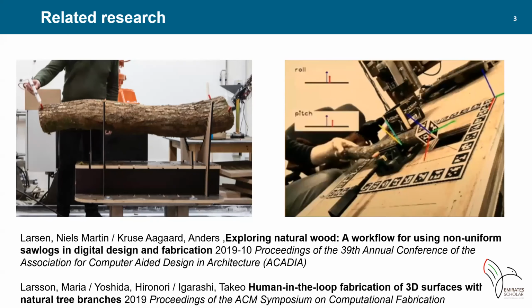There have been cases of direct processing of logs before our study. Most log processing systems do not allow free repositioning. This is because if the posture of the workpiece during machining is different from when the shape is measured, the difference in posture needs to be handled, and measurement of posture change is not easy. In this case, the posture is tracked by attaching a jig to logs, which enables machining with different postures. However, it is necessary to prepare as many jigs as there are logs, and the jigs themselves become obstacles to machining.